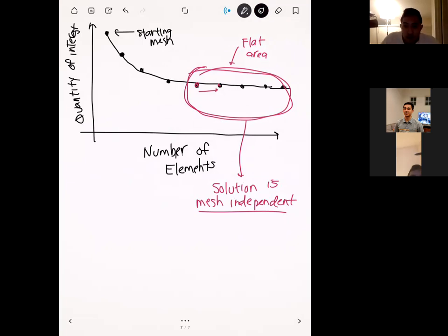So is this a built-in feature in Ansys, or do we need to collect data to create a plot like that? I think there is a feature in Ansys for this. Someone told me about it at the end of last year, but I haven't looked at it myself. Usually something like this is not that bad to perform manually, and I think you have more control when you do it manually too. If you vary the mesh yourself and have Excel open at the same time, then you can track these things yourself. That's how I've typically done it too.